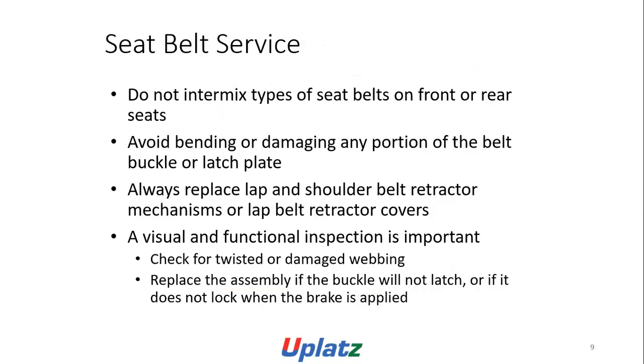Seat belt service: do not intermix the types of seat belts on the front or the rear seats. Avoid bending or damaging any portion of the belt buckle or latch plate. Always replace lap and shoulder belt retractor mechanisms or lap belt retractor covers. A visual and functional inspection is important. Check for twisted or damaged webbing. Replace the assembly if the buckle will not latch or if it does not lock when the brake is applied.